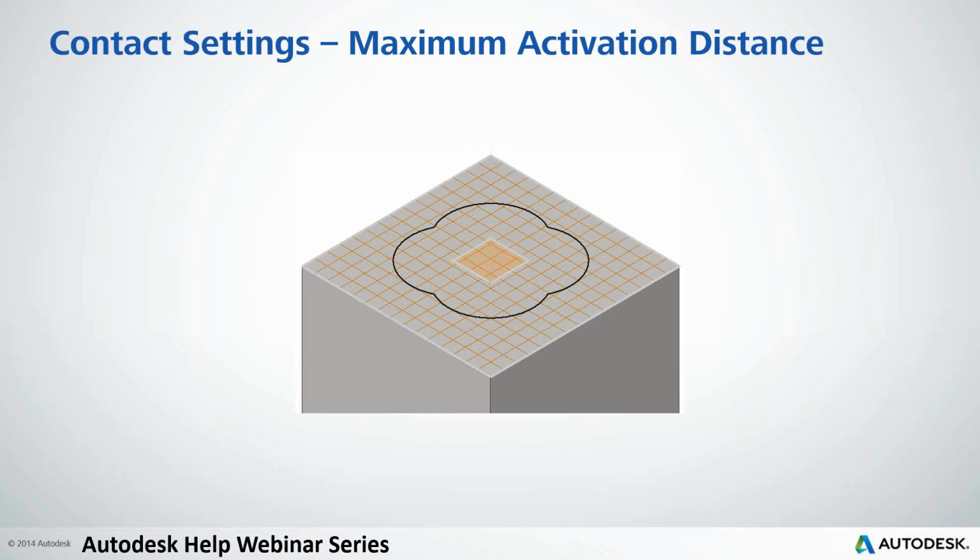Now this is important, especially when you have large motion in a model. You want to make sure that you've appropriately set up your activation distance to encompass the entire regime that you're expecting the part to move. If you don't set up enough, what you'll actually see is the part will just fall off because you no longer have a contact between the 2 components occurring.